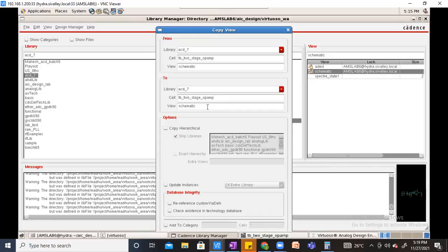The inductor in the analog library has Q values, one inductor where we can set the Q value of that inductor, and then there is one normal simple inductor that has only inductor values. So should I take the Q value one for that schematic, like the VCO?